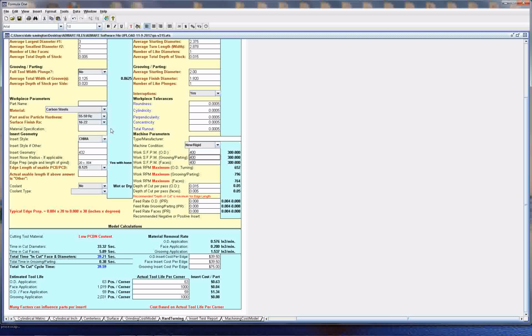Well, let's go down to 300 series stainless. It's not applicable. It's not a place that can be used for hard turning. Not considered a good application. Let's assume that we go to gray iron. Wow, big difference. Now we go to high PCBN content, solid PCBN. But we have a lot higher potential than we had with the hard steel.